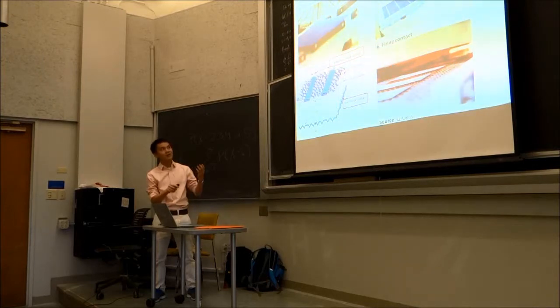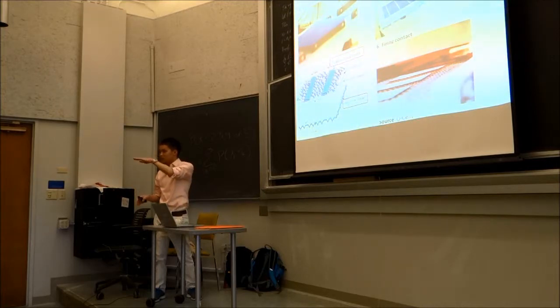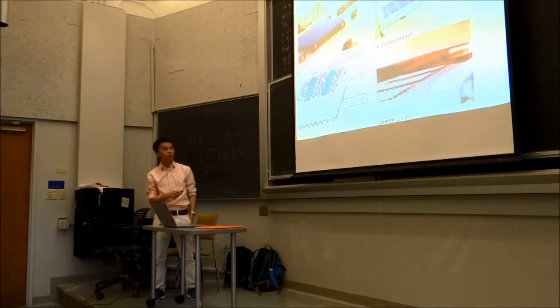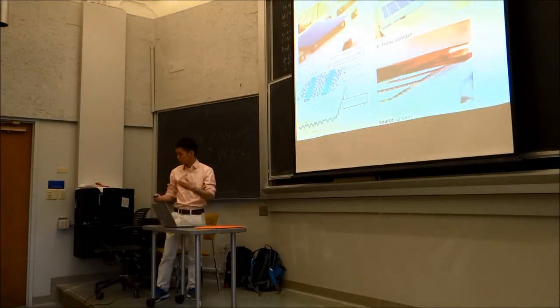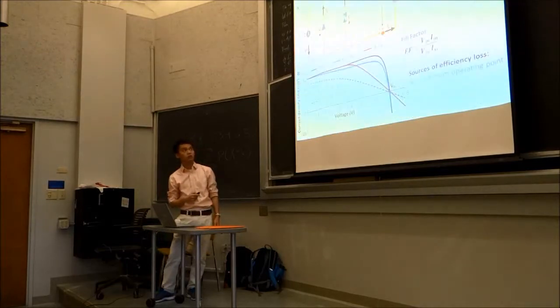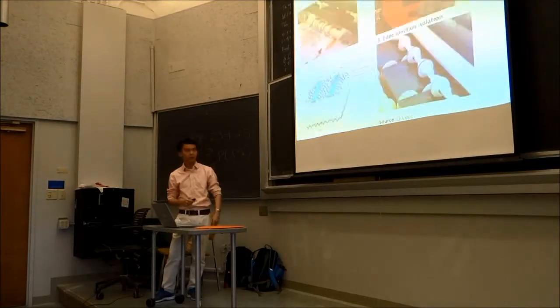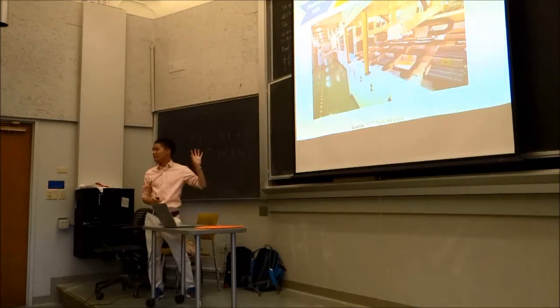What the screen printing does is that they have some kind of screen with some openings, and you put the silver paste through the screen, and where you have openings, it drops through, and you have the contact like that. And also you have back contact. After you have printed them, you put them into a furnace again for firing at high temperature to activate the contact, to improve the ohmic contact between your metal contact here and your silicon material to reduce the series resistance we talked about here, series resistance, right? Firing contact, etc. Okay, so that is making the cell.